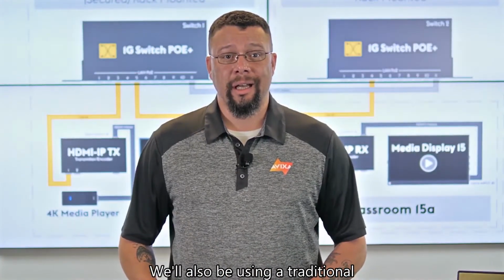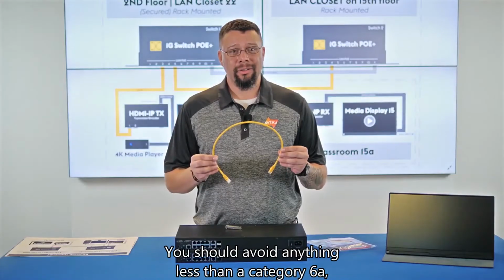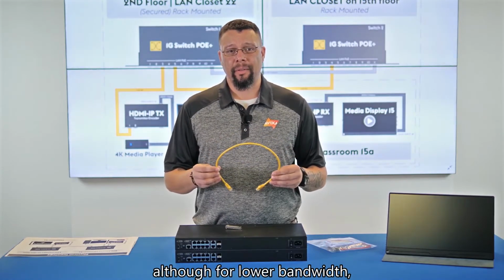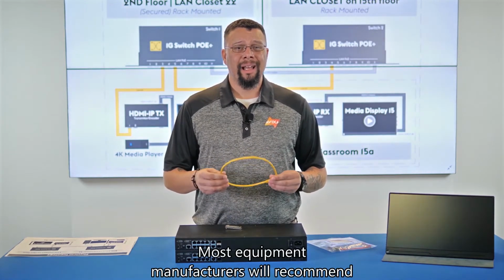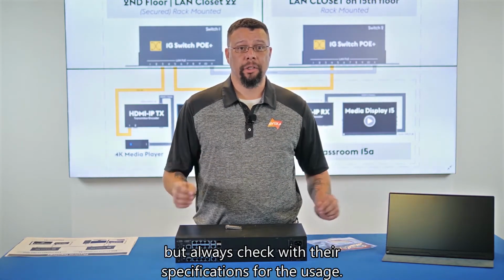We'll also be using a traditional twisted pair copper category cable. You should avoid anything less than a category 6A, although for lower bandwidth, Cat 6 or even Cat 5e may also work. Most equipment manufacturers will recommend a prefabricated cable, but always check with their specifications for the usage.